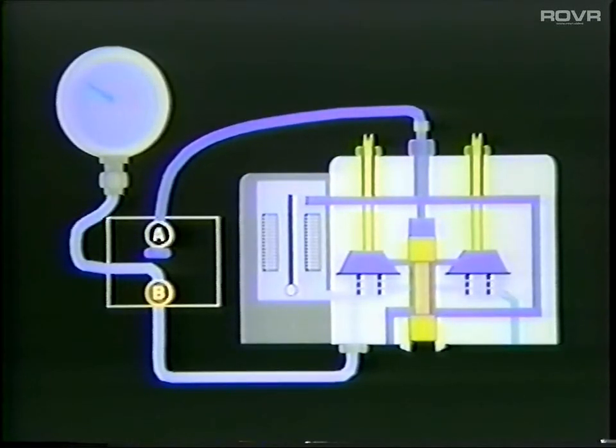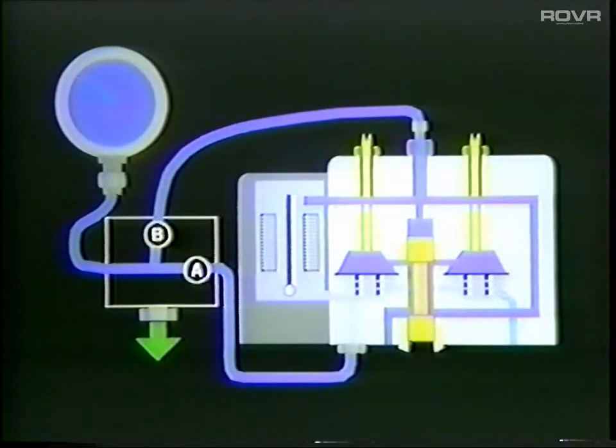With the two-valve version gauge, if valve A is opened and B is closed, system pressure is connected to the gauge. And conversely, if valve B is opened and A is closed, lower chamber pressure is registered. With a single valve gauge, when the valve is closed, the system pressure circuit is blocked, and the gauge will register lower chamber pressure. When the valve is opened, although both pressures are connected to the gauge, system pressure is the higher of the two. Therefore, system pressure is registered.